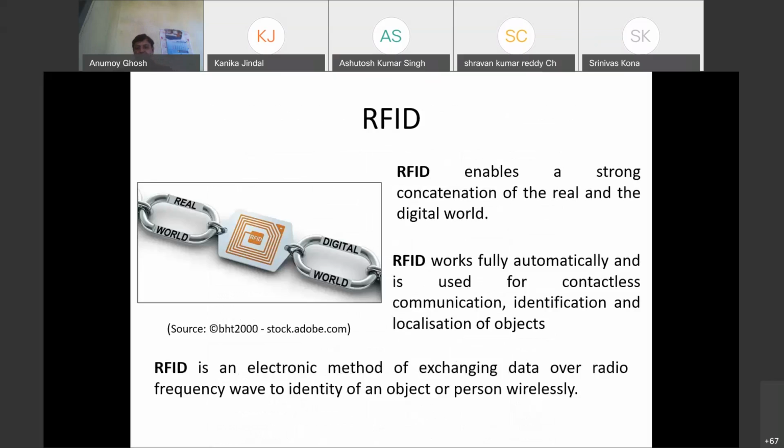This is the basic design of an RFID. And always keep one thing in mind: RFID works in the digital domain. That means the data which is stored is always in the digital domain. The stored data is first modulated, and then that modulated signal is up-converted to a gigahertz frequency, and then the RFID antenna radiates that frequency. But the data in the RFID chipset is always in digital form. Keep this in mind. It is not in analog form.